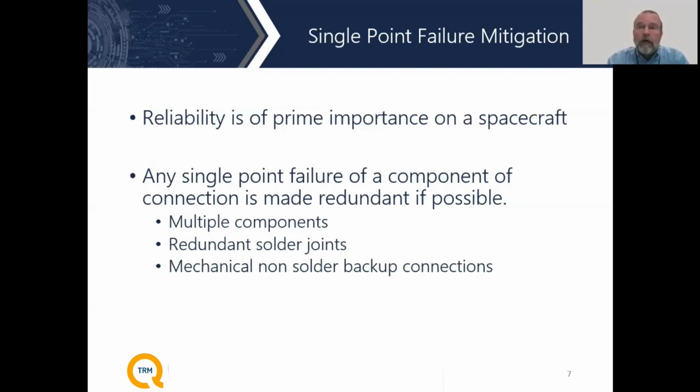If we are doing very low frequency components, and we have wire wound transformers, we double wind all the transformers. And as far as the rest of the design is concerned, if a component might fail, very often we'll use two of them in parallel, depending on the exact failure mode of that particular component. Then if a solder joint fails, at least the part will continue to function. It might not be totally spec compliant, but the part will still continue to function.